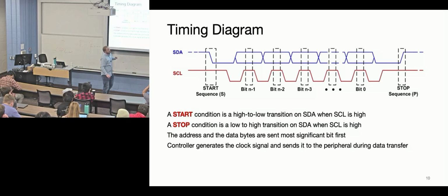Now this is a weird protocol where the clock edges, both edges, happen inside the data. Before we talked about how there was a toggle or setup phase, and then there was the clocking in edge. Here, both things occur. So you clock up and down inside the data window, and this is the condition in which data is clocked in. The clock is not transitioning when the data transitions.